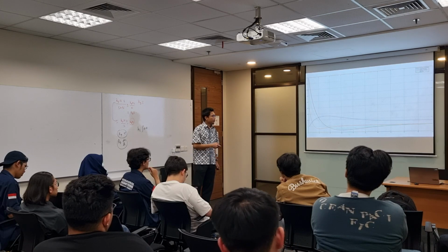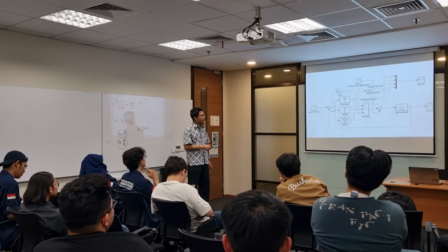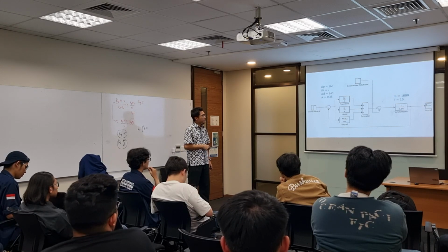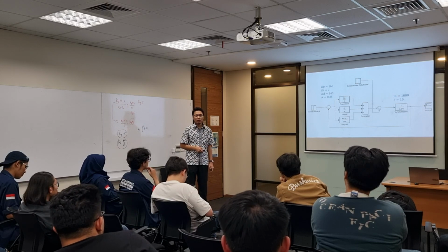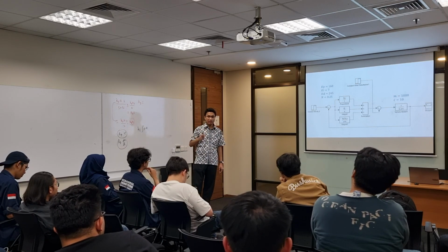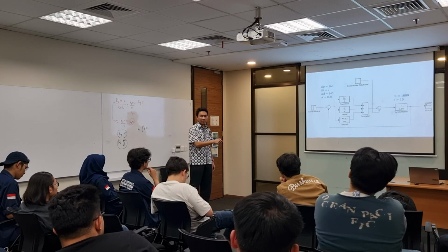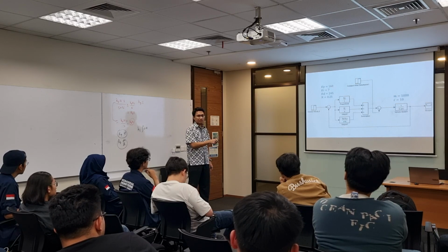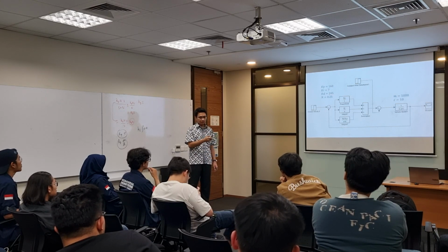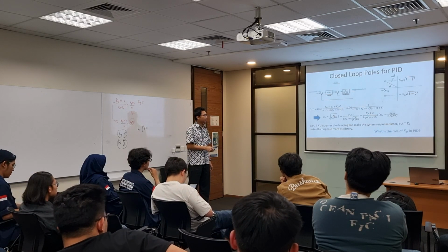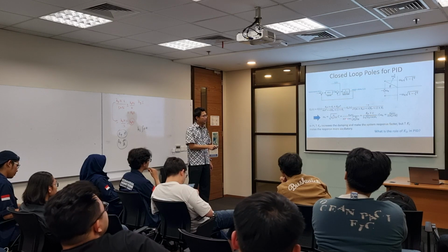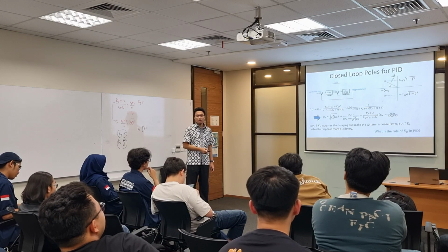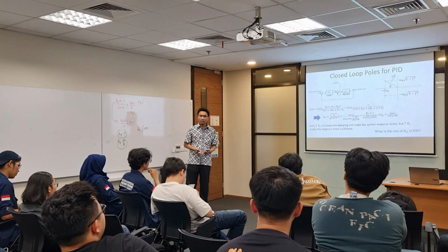Let's say you are not patient, and I want my derivative control action to be very large, so you enlarge this, let's say 2000 or 5000 compared to 160 and 7. Okay, 20 times the current derivative control action. What will happen here? It is very, very small, so your response will be very, very slow.